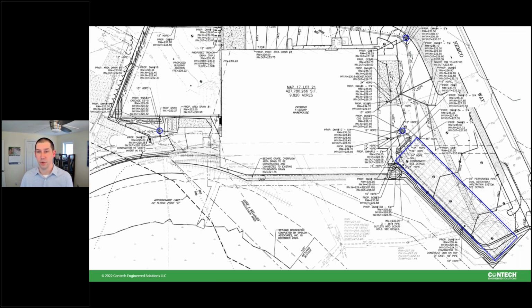We looked initially at 72-inch, and then we looked at a 24-foot CON/SPAN using one large basin with 60-inch pipes at a higher elevation to connect back over. We looked at 120-inch, I think we looked at 108-inch if memory serves, ultimately landing on 96-inch. In this case, as Yelena was just mentioning, sometimes you can go big, sometimes you can find the middle ground if you're using perforated. It's exactly what we decided to do in this case.